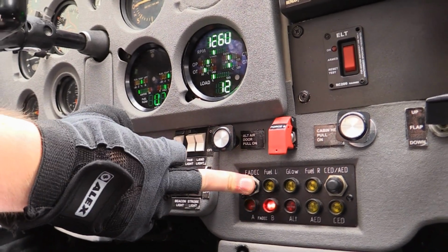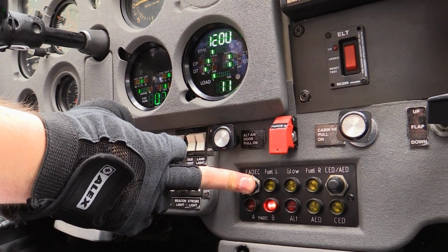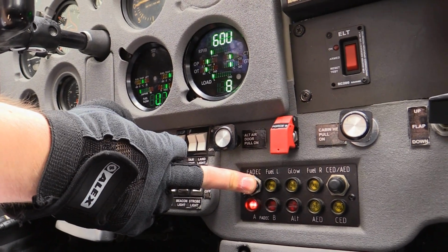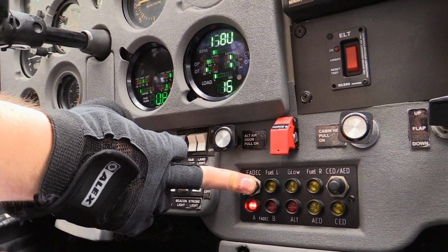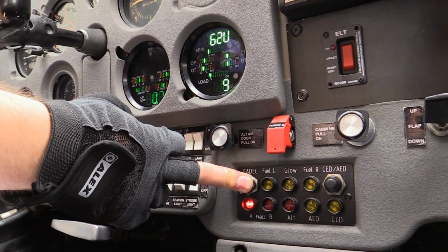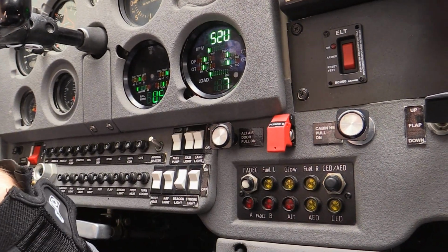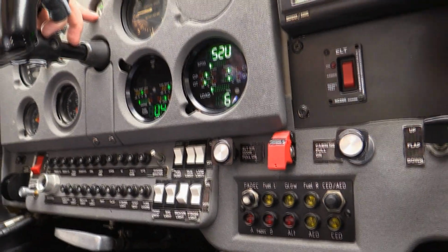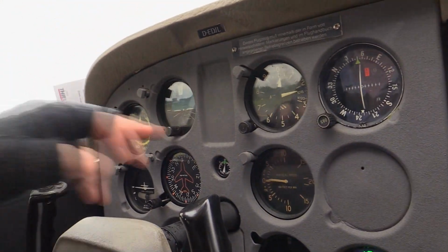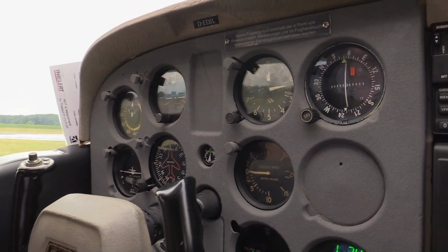Both units are on. Now only the B unit is running, and that works perfectly. Now idle RPM switches to the A unit. A unit is running up. And that also works perfectly. Light extinguishes, everything is fine. We got good suction here for our gyro instruments. If I just advance the power a little bit, you can see we are already in the green. So our suction pump is working.